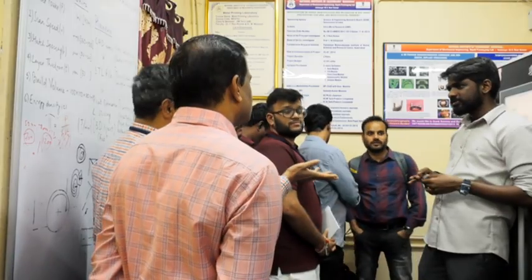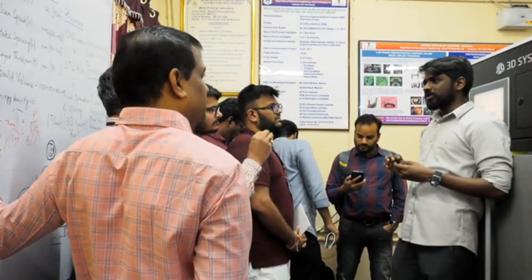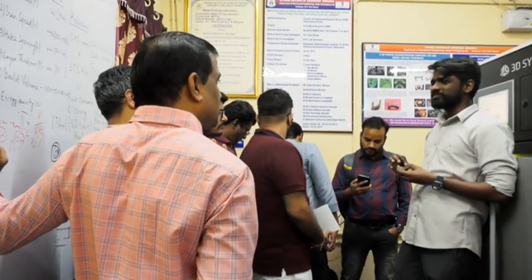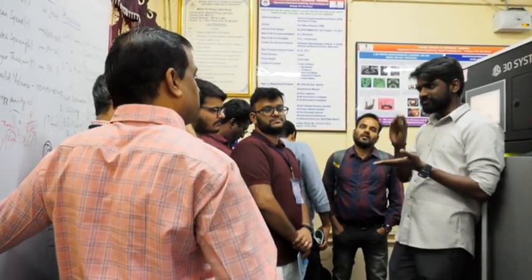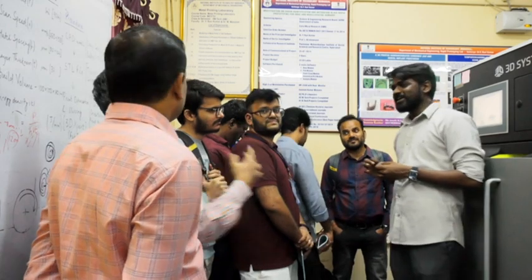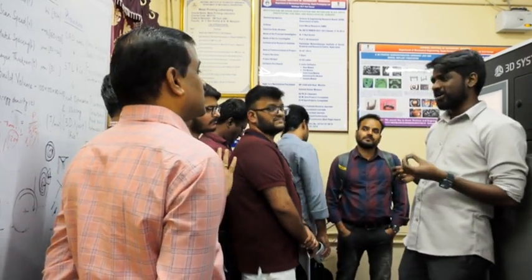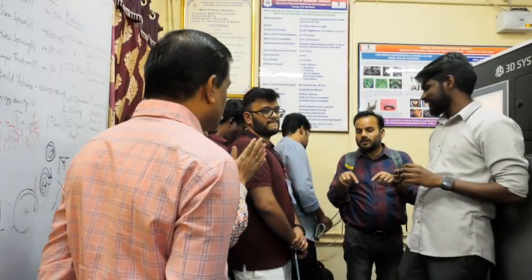Generally for PBF, you need large quantities of powder. You don't want to print small samples? Not that much, sir. Compared to other processes like DED, we do not require that much. DED is much better, I can put 1.5 kg of powder. In DED, the hopper quantity will depend upon the build platform size.